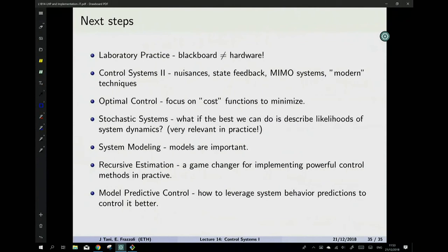Well, the short story is time delays include a lag. Lag reduces your phase margin and sends your system unstable. How do you fix them? There's no golden rule to do so, but lots of approximations. We will talk about these things later on. So how do you go on from here?